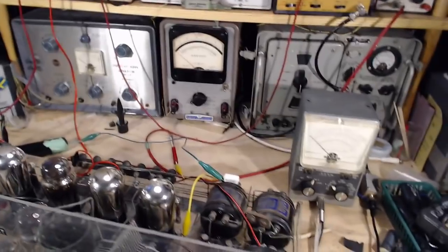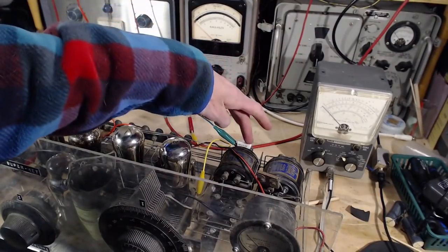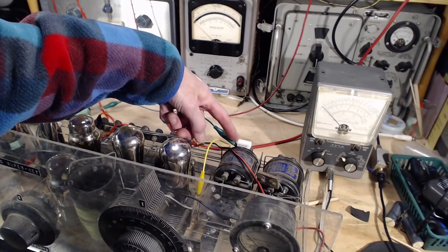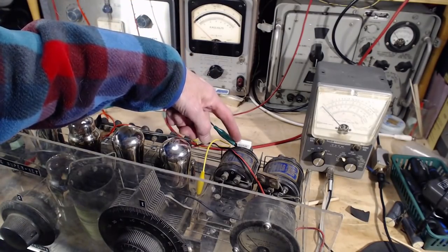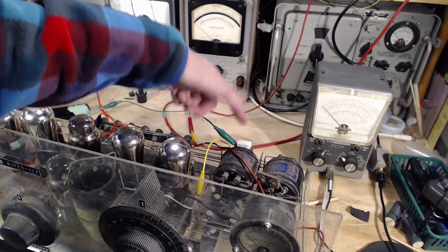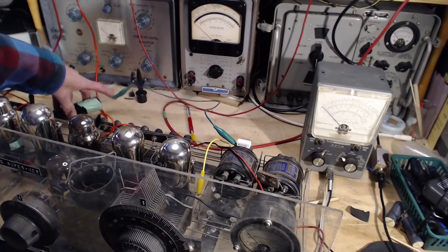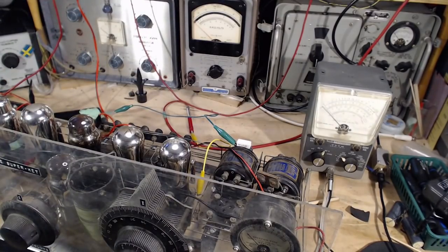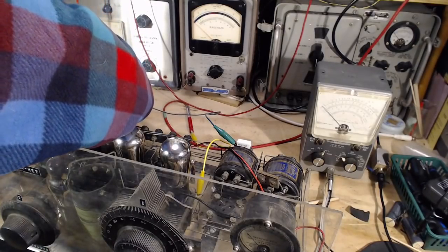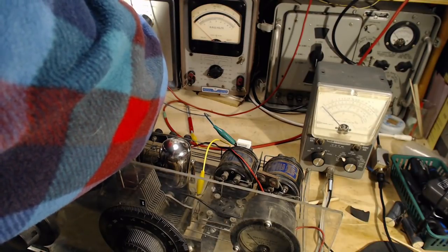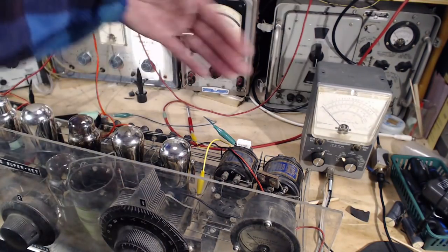I have installed a 1000 ohm resistor here because of the open primary, and I've also connected a lead to the tube side of this resistor, and it's going out to my signal tracer, which should have made a noise there. Why did it not make a noise? There we are. So we can listen to any audio that might come out of here.